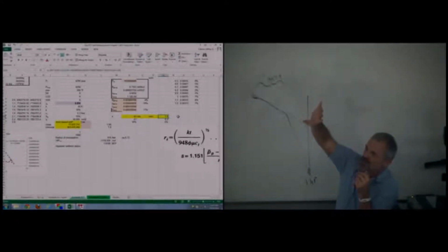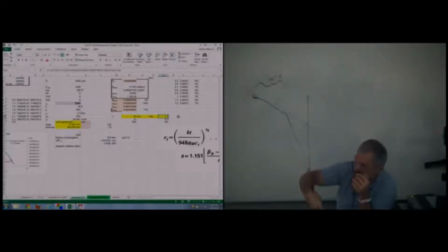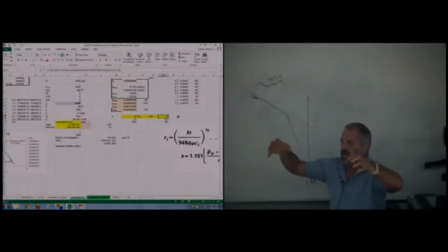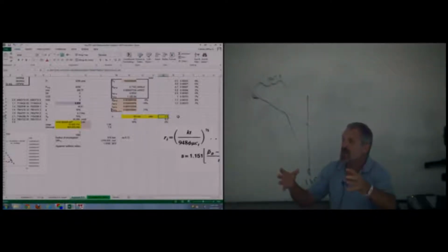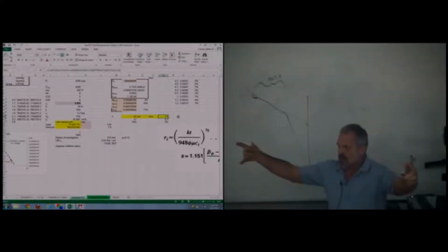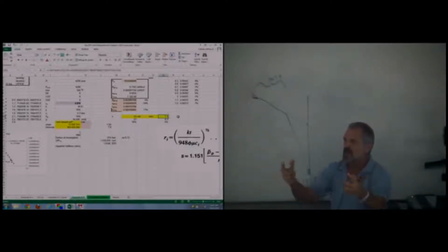You could drill into the top of a reservoir, but not fully penetrate the reservoir, okay? And your flow wouldn't really be radial at first because it would actually be semi-hemispherical, okay? So you would get a lot more flow, your rate would be high. But when the rate's dominated by the radial flow in, you see, you're not fully penetrating the reservoir, so you could have a partial penetration contribution to skin other than just damage.